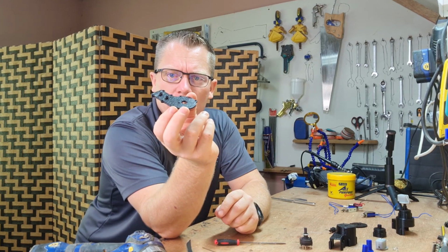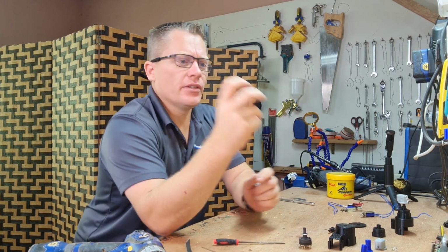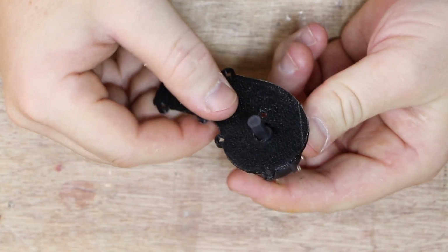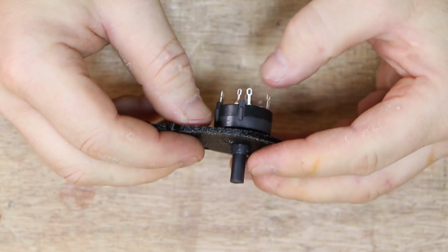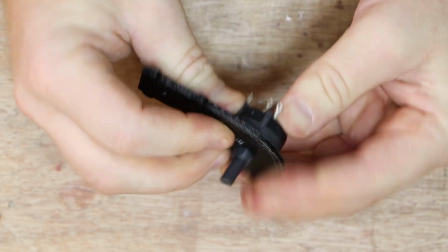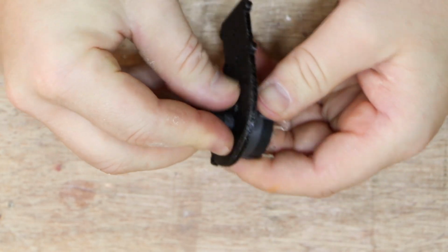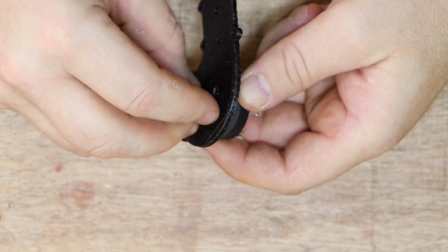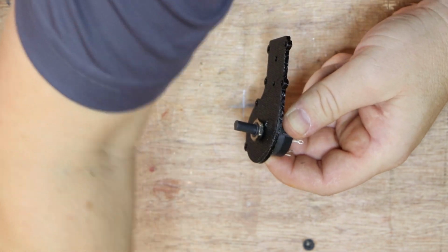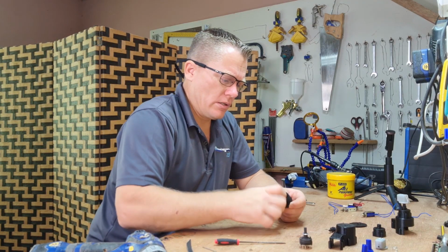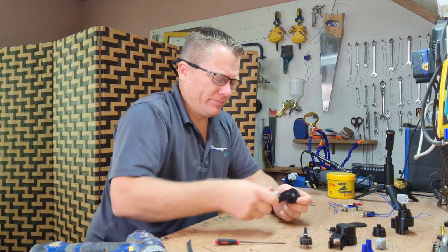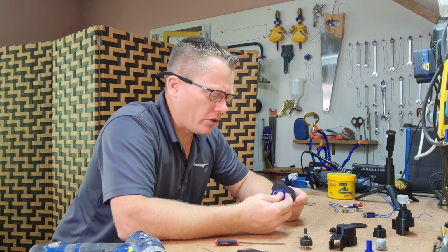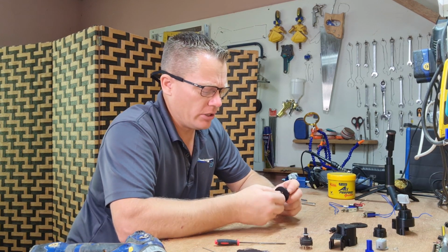The studs that are sticking out the bottom need to go on the outside, and the rotary switch goes in from the outside up, and there's a little locating spigot again with a hole that will help orientate it in the right direction, and we put the nut on. Tighten that into place, and hopefully the activation cam should go directly over the switch.